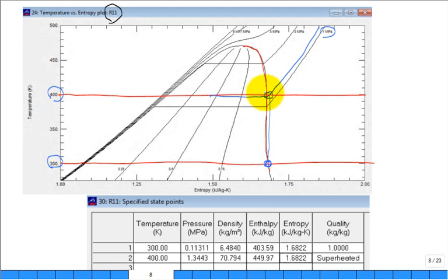And that's what we find. If you take a look and say, okay, I'm going to start with this low temperature, this is my entropy, do an isentropic kind of backward look at it up to this high temperature, it's slightly superheated, but it's pretty close to the dome, and it's at about 1.3, this is 1, this is about 1.34 megapascal. Actually, that's pretty good.